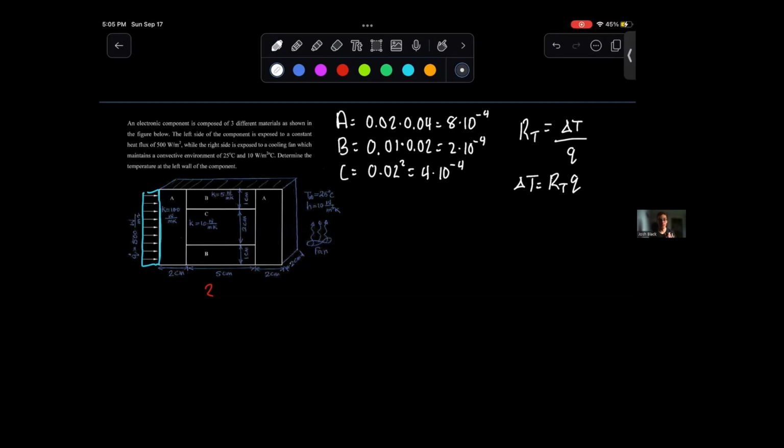This is where you got to pay attention to detail. We know that heat flows from hot to cold. We are told that the heat flux is positive and goes from side 1, where T1 is, to side 2. Therefore, what's going to be hot, T1 or T2? We flow from left to right, hot to cold. This shows that T1 is hotter than T2.